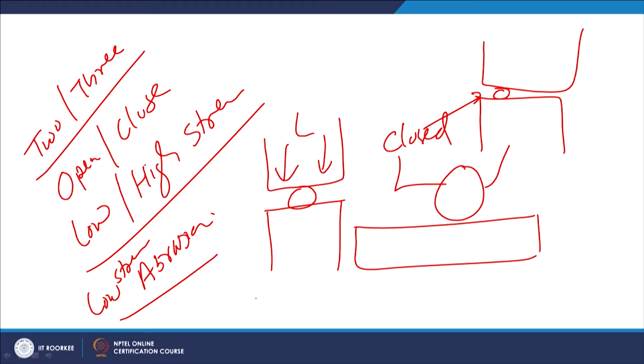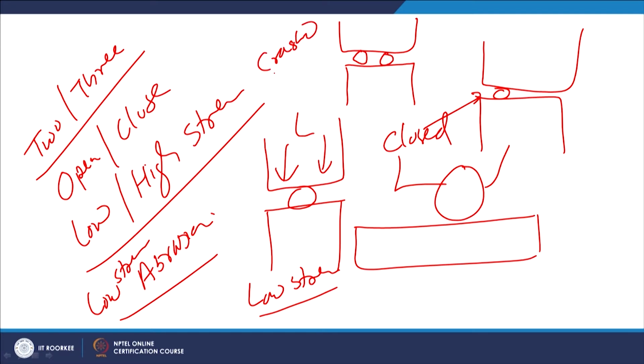That is the state of low stress abrasive wear, while in case of high stress abrasive wear, wherever the particle is present, loading is such that the abrasive particle is crushed, broken and damaged. So, this is the difference. Under low stress conditions the particle largely retains its size and shape, while under high stress conditions the particle is crushed.